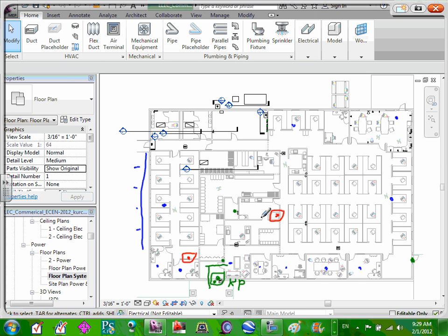If you have people in wheelchairs that are getting into your space, I think you should give them 120 seconds, because to get in through 2 doors and get situated and get to the keypad to where you can enter your code, you need a little bit more time. So it's not a standard time, no, but most systems allow you different amounts.